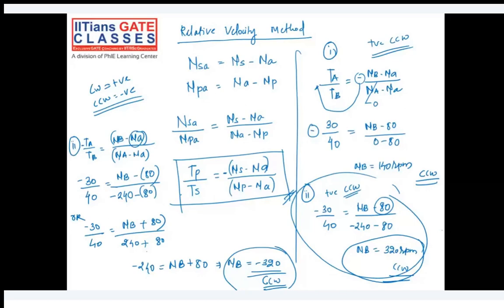We also studied the different types of gears depending on the parallel shafts, intersecting shafts, and skew shafts. If we have parallel shafts, we can have a spur gear, spur rack and pinion, or helical gear, or double helical gear. Okay, and we have studied the comparison between them, especially regarding the axial thrust and the noise.